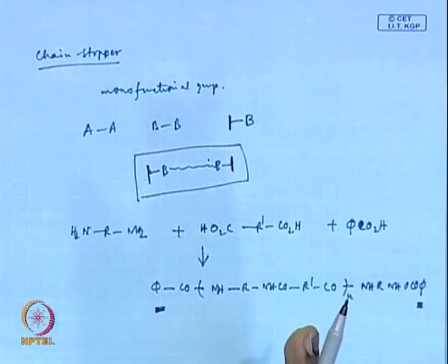But in the first case, if you stop the reaction in between at some conversion level, then after you go through the compounding and processing step, in the final article, final application, the molecular weight will vary from your target molecular weight. That means the properties also will vary.